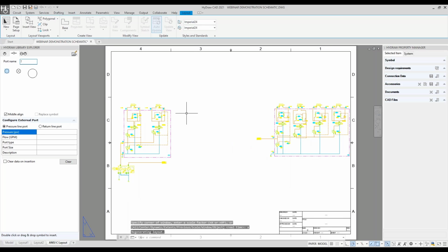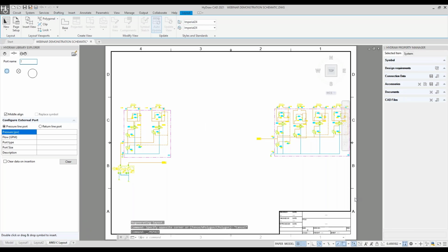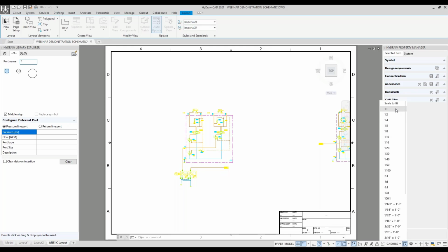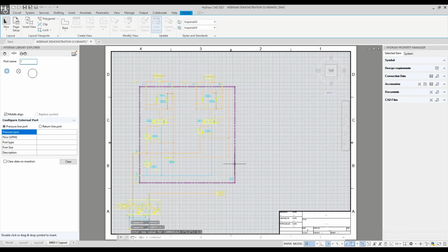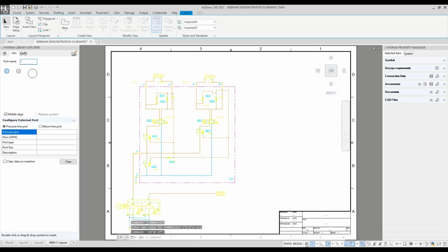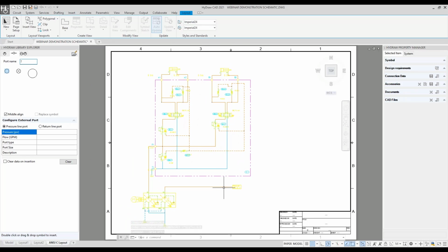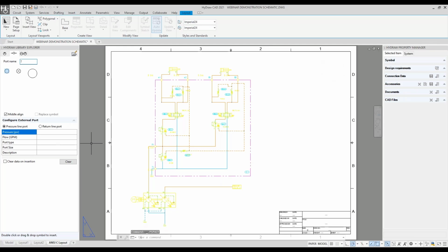So now this is actually showing us the model space on paper space. And if I want to double click into here, see the viewport that I just created gets a much darker, thicker line, and we can actually manipulate that in here. And since schematics are technically drawn 1-to-1 scale, you can actually come down here to the bottom right. We can actually say 1-to-1 scale and bring that in. And it looks a little gross right now, but that's just because I have my grid on. So I can now move this around and get that into the view of where I want it. And then to leave, I can either double click outside of the viewport or type P space to toggle back and forth between model space and paper space.